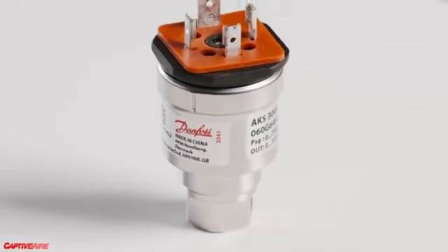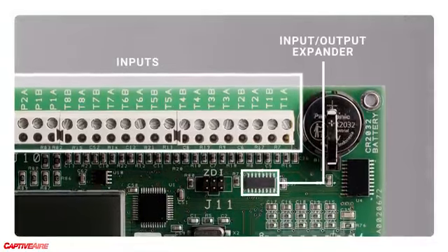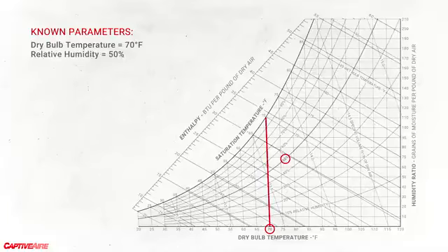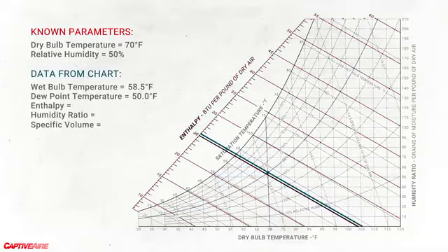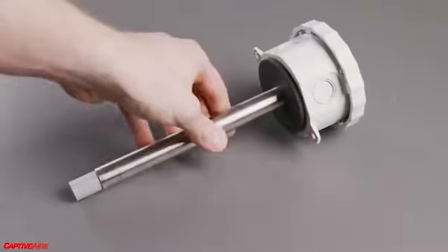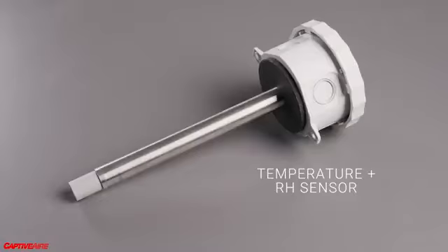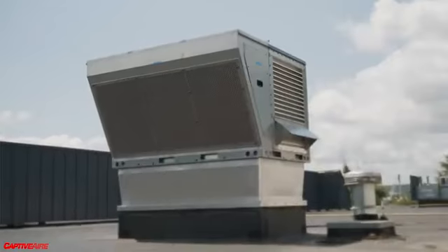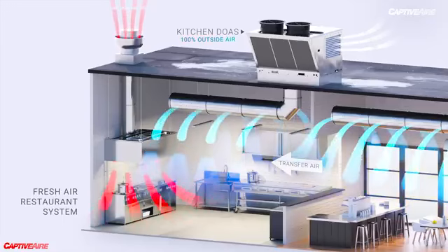So we use many input devices to gather data, but it's still important to be efficient. If you remember from our psychrometrics video, we can measure any 2 parameters of moist air to calculate any other property. So instead of directly measuring things like dew point, wet bulb temperature, or vapor pressure, we calculate these values using just temperature, relative humidity, and the corresponding equations. And this is extremely useful for units that refrigerate or temper the air.